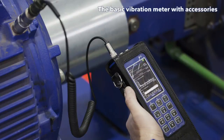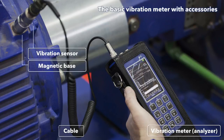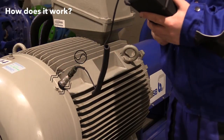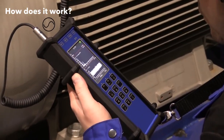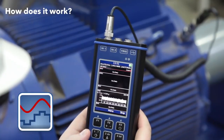Let's explain what the basic vibration measuring equipment looks like. It consists of the following parts: a vibration meter or analyzer, a cable, an acceleration or vibration sensor with a magnetic base. How does it work? You place the acceleration sensor on the measuring point. This converts the vibrations into electronic signals. The signals are transmitted via the cable to the vibration meter or analyzer, and the signal is processed into the vibration values which you can read on the device screen.